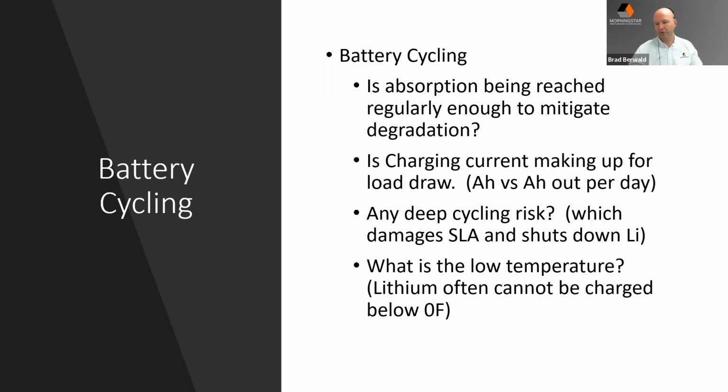And also, what are the types of temperatures that the system is actually seeing, not just in the ambient air, but actually at the battery? Because as we are moving to a lithium storage future, we know that lithium has a few more limitations, a lot of benefits, but more limitations regarding low temperature charging.